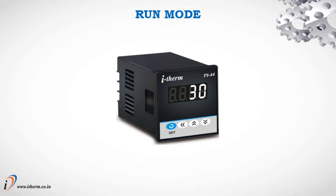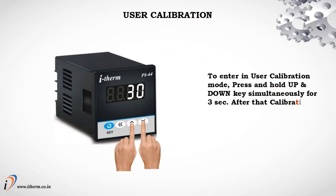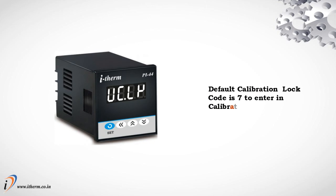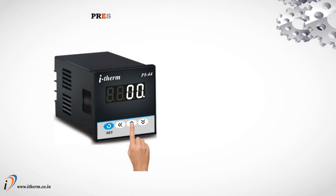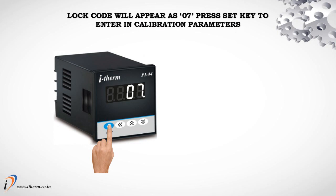Run mode. To enter in user calibration mode, press and hold up and down key simultaneously for 3 seconds. After that, calibration log code parameter will appear. Default calibration log code is 7. To enter in calibration mode, press up key to make unit digit 7. Log code will appear as 07. Press set key to enter in calibration parameters.